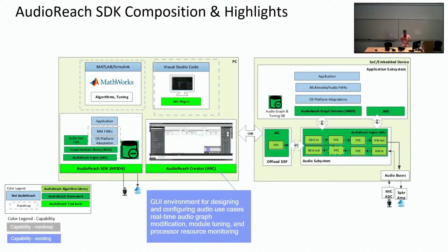In that mode, you'll be able to tune the modules by doing set param and get param, in order to tune the audio processing modules at runtime. You'll even be able to do real-time audio graph modification. That means while the use case is running, you can add or delete audio processing modules in the use case graph without even stopping the use case.